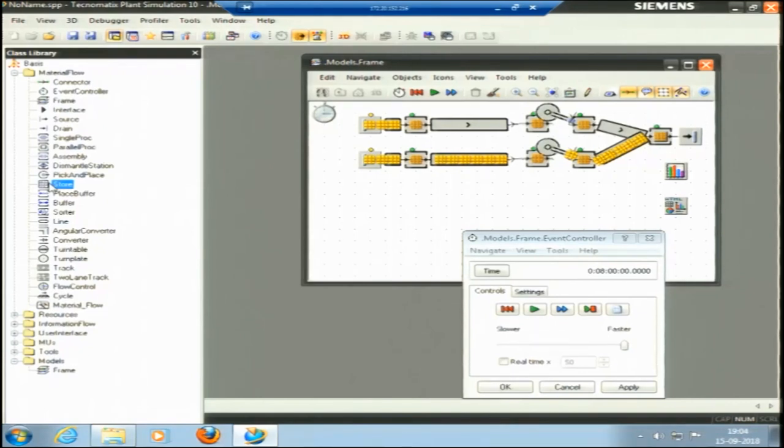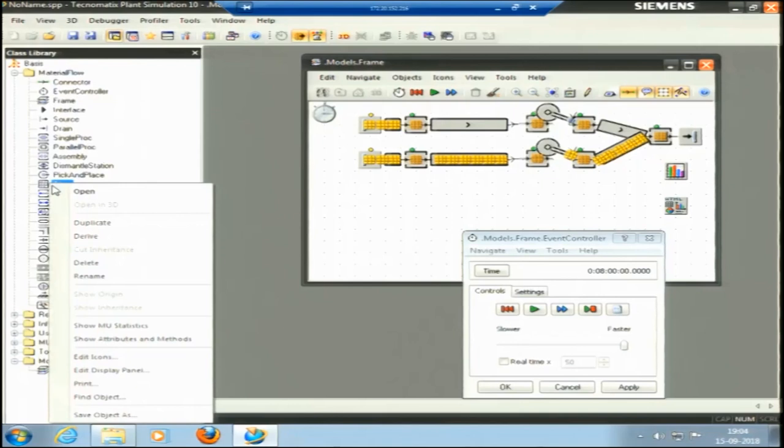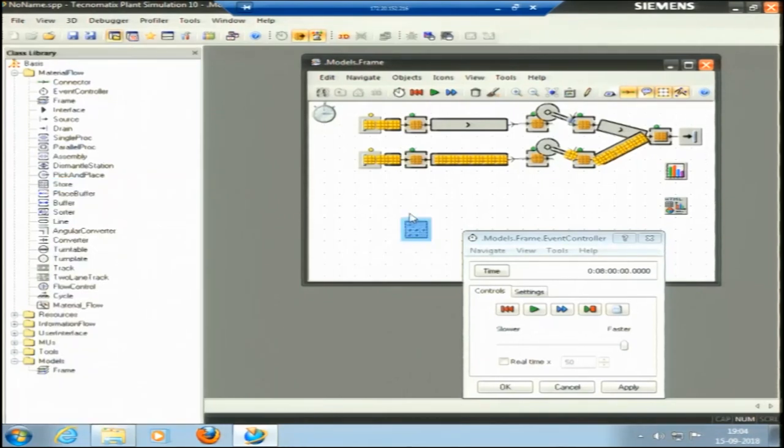You can define the size of the store by specifying its X and Y dimensions, like how many pieces. For instance, this is a store in between. We can also add the buffer in between. For instance, there is a big blockage of the materials in one side. We can add a buffer in between. Okay, so the process doesn't have to wait, we can put a buffer. The buffer capacity would be there. Buffer capacity that it can hold, let me say 100 pieces in a day. So, whenever the next process is free to pick a piece from here, it can pick the piece from the buffer. So, that buffer can be used here.